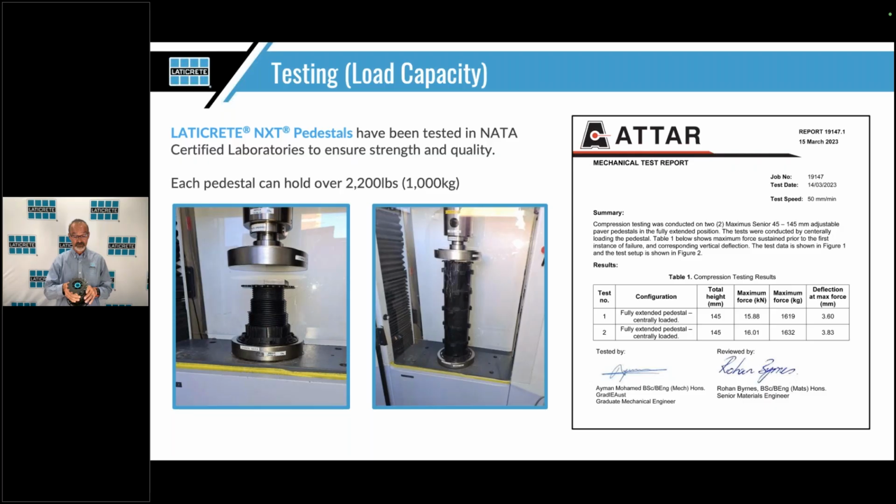Also, one thing that we didn't have a slide for, but I want to mention it because it came up in the seminar yesterday. Let's say it's called out for a center, kind of like the number 5 on a dice, and they want a center, you just don't put in the tab spacer, bring this up in the middle and thread it in, and you're good to go. So once again, you've got basically 3 main SKUs, the mini, the max, and the extender to get the full range. You've got the slope correctors, the rubber shims, and always remember when you buy the pedestals, you will always have the tab spacer included in it. You don't have to order that separate. These come separate. Anything specialty comes separate.